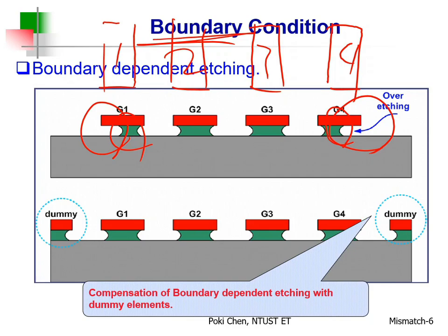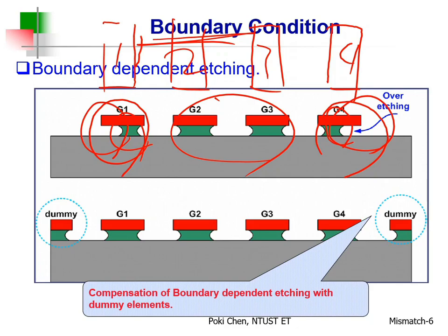So layout engineers will always think after fabrication, all those 4 will be the same because I copy and paste all of them. During layout, they are exactly the same. I would like to tell you, sorry for that. After fabrication, 1 and 4 will become slimmer than the middle 2. Got it? That is destiny. It happens always instead of randomly. So we call it systematic mismatch.